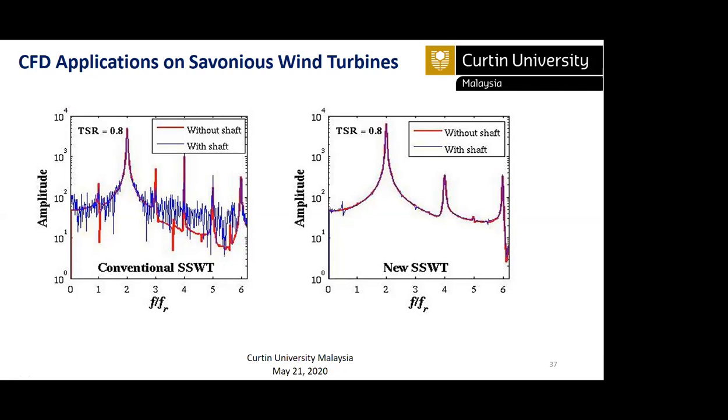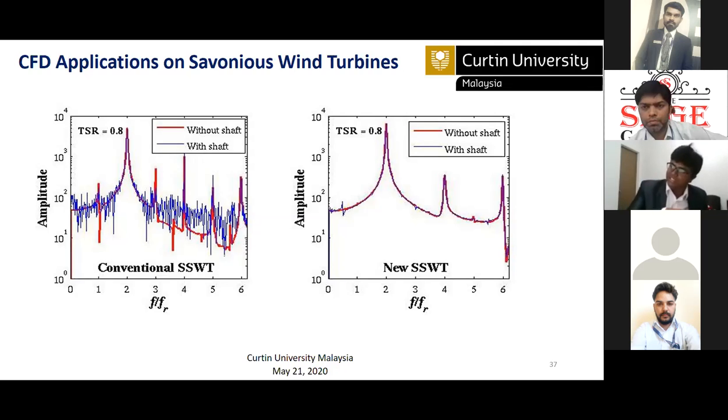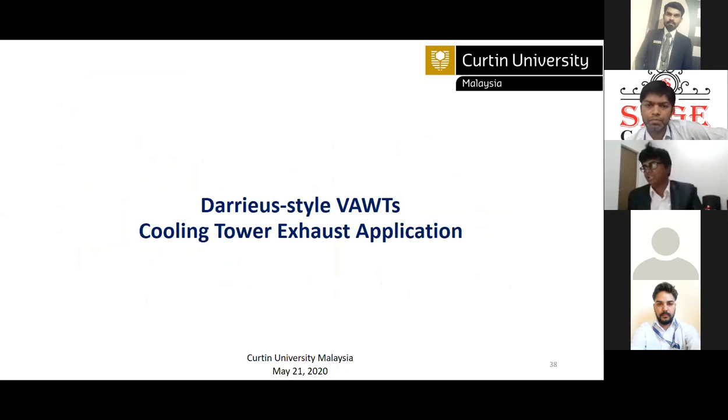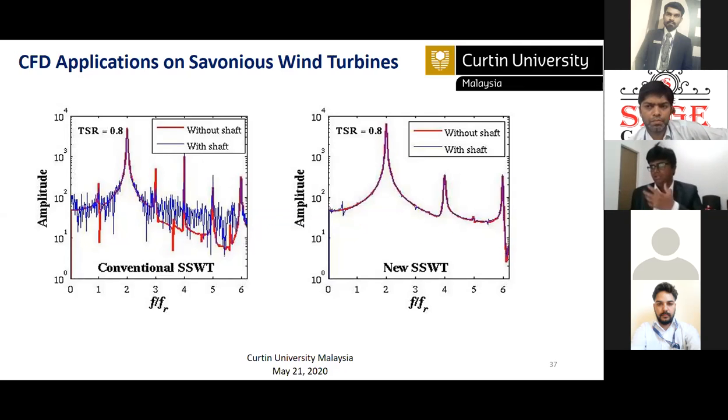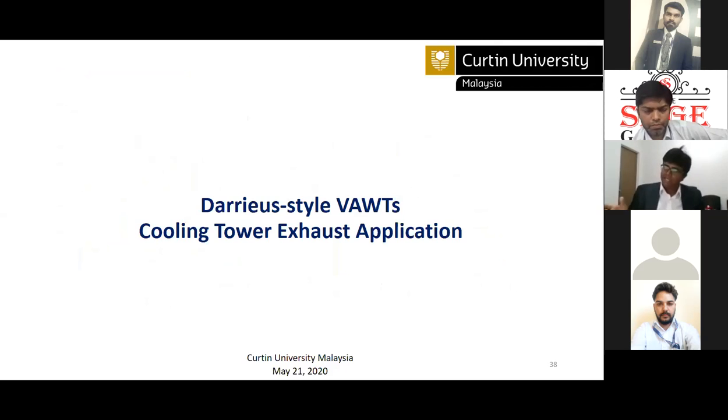So that is a very good reason, and we identified the possibility of power reduction for the semicircular turbine. In the new design, because of the long handle, the vortices caused by the shaft are mitigated before reaching the returning blade suction side. That means the negative effect is not significant in the new blade as compared to the conventional blade. That was a very interesting finding from that research, and it was presented at a conference in Italy and well appreciated. After that, we did some research on various types of vertical axis turbines also.